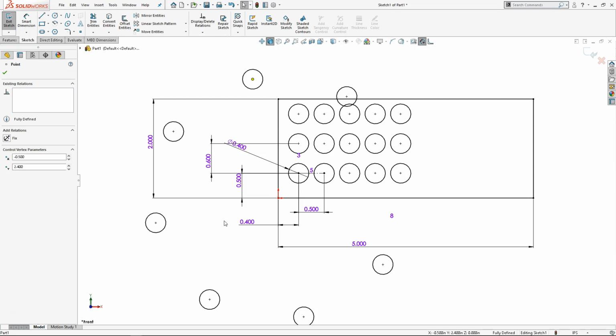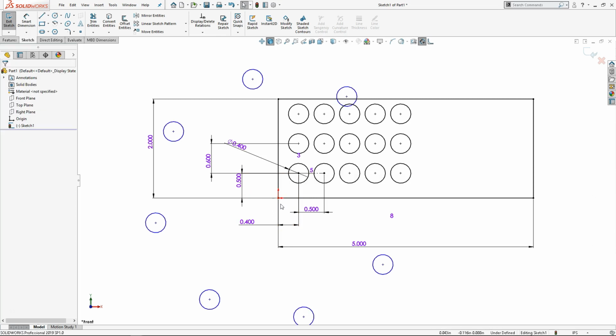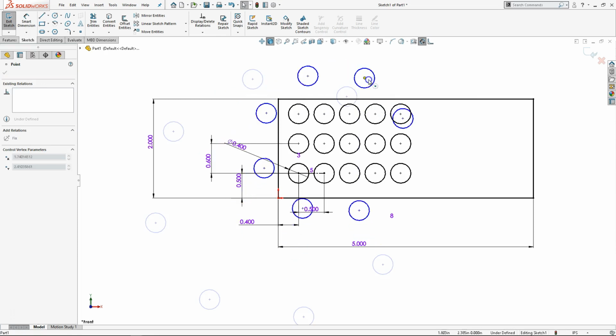And the Hole Wizard takes those points and does an instance count, and you will find that in your drawings you have 8 holes, but it lists 9. And the 9th is that point that it put right at the center. All right, so a lot of times we'll take and see if I can delete that point. Everything goes back to being underdefined. It will stay in the circular pattern, but now it's free to orbit.